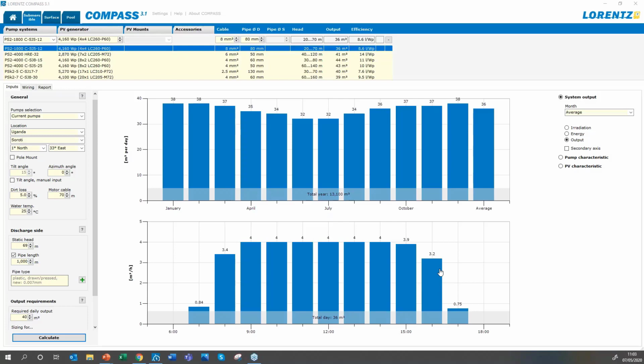As I mentioned earlier, we are typically sizing with no batteries. If you look at pump power, sizing battery systems for pumps gets really expensive quite quickly. Of course, you can run anything on batteries. What we're really trying to do 99% of the time is pump water during daytime and store it in an elevated tank, so we store both water and energy. But where that's not possible, it's often more attractive to use a generator rather than batteries. Battery sizing for pumps tends to get quite big and expensive very quickly.